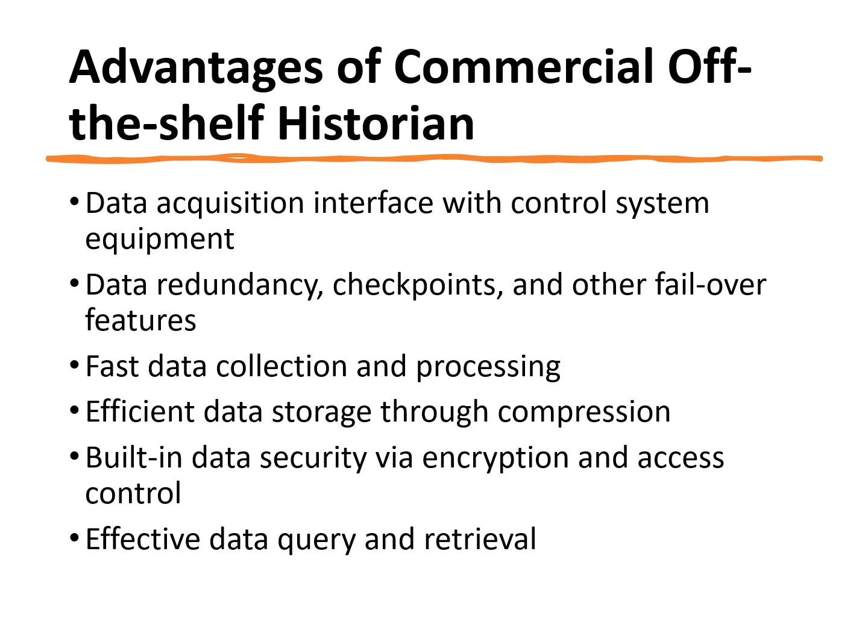the availability of a data acquisition interface with control system equipment and intelligent electronic devices, the robustness features of data redundancy, transaction checkpoints, and other failover features, the capability of fast data collection and processing, the provision of an efficient data storage through compression, the built-in data security through encryption and access control mechanisms, and effective data query and retrieval.